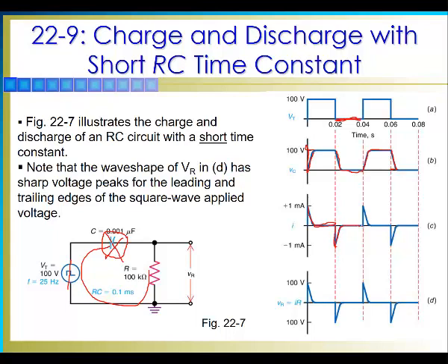Fully discharged, it gets to zero, and then we apply the voltage again. Now the current jumps again to 1 amp, and then starts decreasing as the capacitor charges until it's fully charged, then no current goes through it. Disconnect the voltage again. Now the voltage is being supplied by the capacitor at maximum in the opposite direction, and it starts discharging again until it gets to zero. That's the behavior of the current on a circuit that has a pulsating voltage source with a capacitor in it.